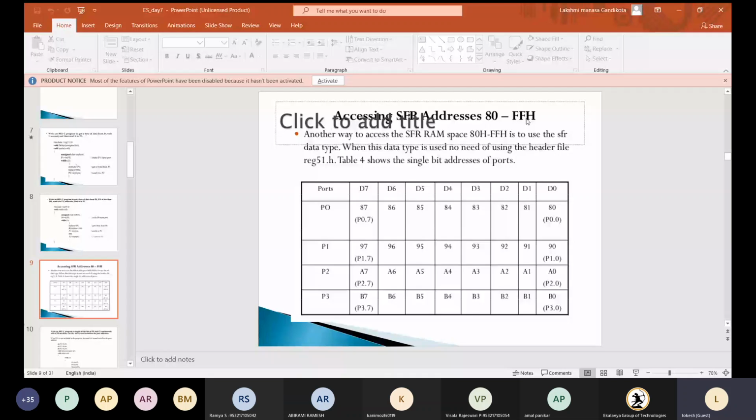Like that, here also we can do the bit-by-bit operations in 8051 embedded C. The bit operations in C are AND, OR, XOR, inverter, shift right, and shift left. Please look at these symbols. Ampersand is AND. We have an OR symbol like this, an XOR symbol like this, an inverter symbol like this, then shift right and shift left. You know this one very well. All of these are supported by C.